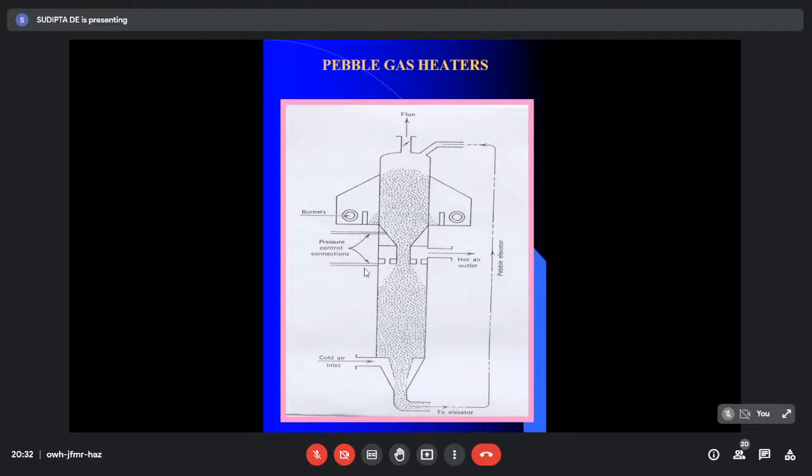From that viewpoint, the heat transfer coefficient increases not only due to the pebbles, which have a certain role that I will explain, but also due to the pebble packing itself that we have discussed. If the packing is better or higher, then obviously the air passage will last for a longer duration, and it will effectively have a longer path, leading to a larger duration of stay within the pebbles. So effectively we'll get more heat transfer, and that will increase the overall heat transfer coefficient.